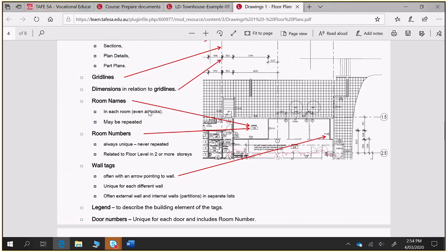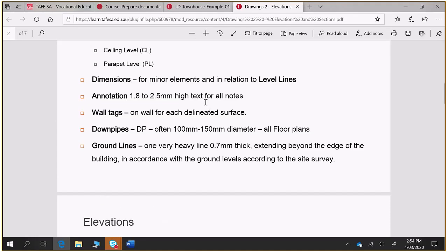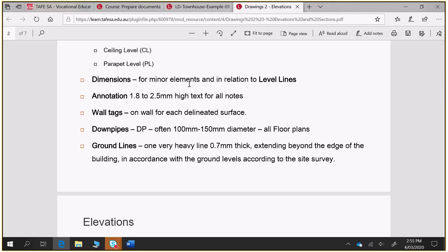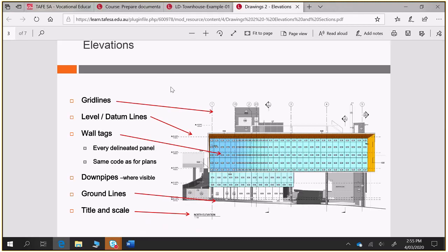Other important notes in regards to drawings is try to avoid duplication of information across drawings. So, that's floor plan. So elevations and sections. So your floor plan is all about showing everything that can happen in a horizontal sense. Things you can't express in a floor plan are how high a wall is. Where you could write that in there, but when you do a section or an elevation, you can express how tall things are. So that's the dimensions I would expect on an elevation, is everything I need to know about how tall something is. And you may also have some of that information on a section as well. If something doesn't show in an elevation that relates to height and dimensioning, you'll dimension that in a section as well.